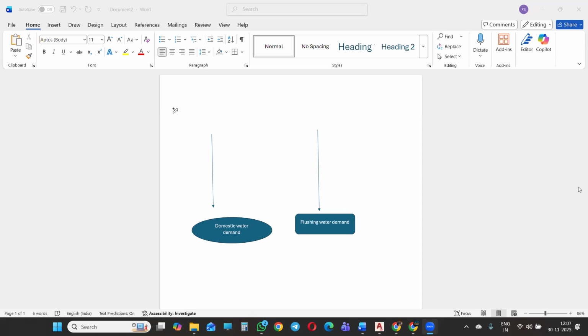For example, in a hospital we are designing for 1,000 patients. That is no guarantee that within 1 year 1,000 patients are going to be treated daily. Or any hotel can be 100% occupied, right? So we have to bifurcate the internal parts of the STP by giving walls, chambers, or volume meters, so that it is not 100% occupied, but the water demand is 100%.